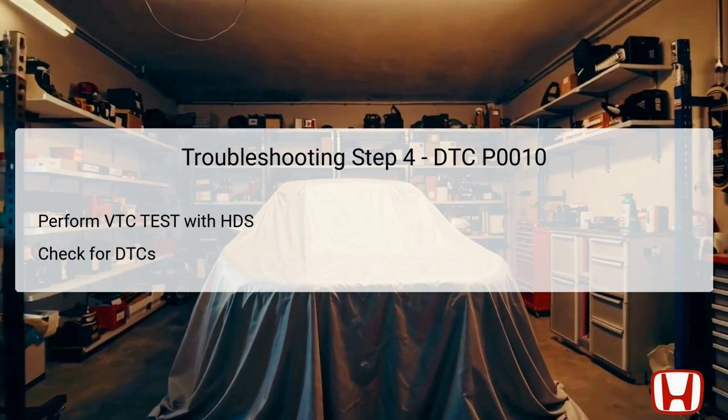The fourth step in the troubleshooting process involves conducting a VTC test using the Honda Diagnostic System, HDS. This specialized test assesses the performance and functionality of the variable timing control system, providing detailed information on its operation. By executing this test, technicians can determine whether the VTC oil control solenoid is working correctly and if the system responds as expected under controlled conditions. After performing the test, it is crucial to check for pending or confirmed DTCs using the HDS.